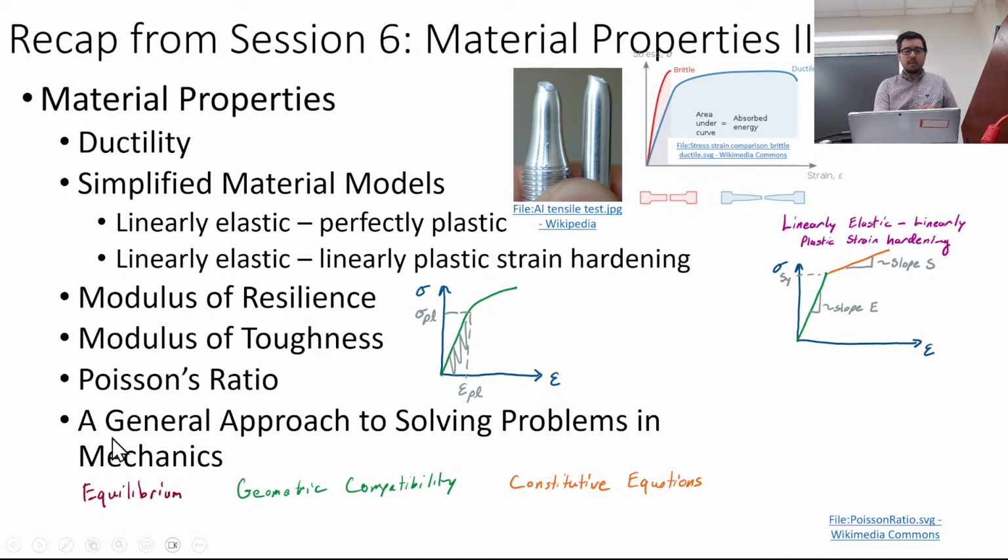And we also talked about a general approach to solving problems in mechanics, and this is based on Crandall, Dahl, and Lardner's book. It has to do with breaking things down into equilibrium, geometric compatibility, and then a set of constitutive equations, which relate the deformation and the forces, or the moments, or the loads to each other, or the stresses.